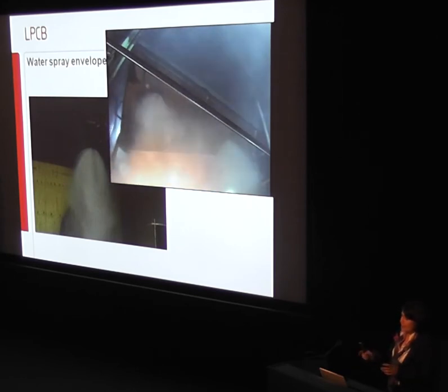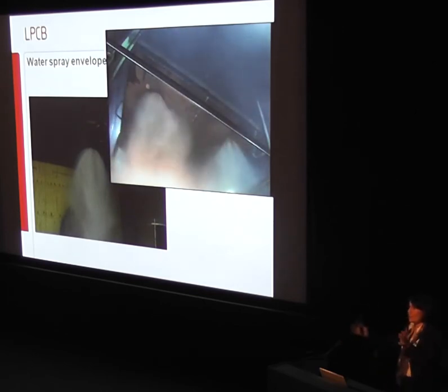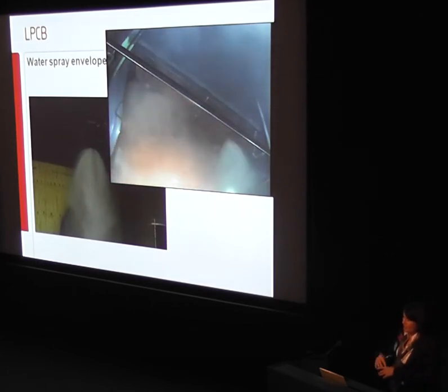The general thought is that water mist completely fills the space, but in actual fact they can be quite tight columns of water, and actually they're only protecting about a 1 metre column below themselves. And you get the benefit of filling a greater space when you've got compartment walls, and you've got the water mist pushed out to the sides and falling down after a period of time.